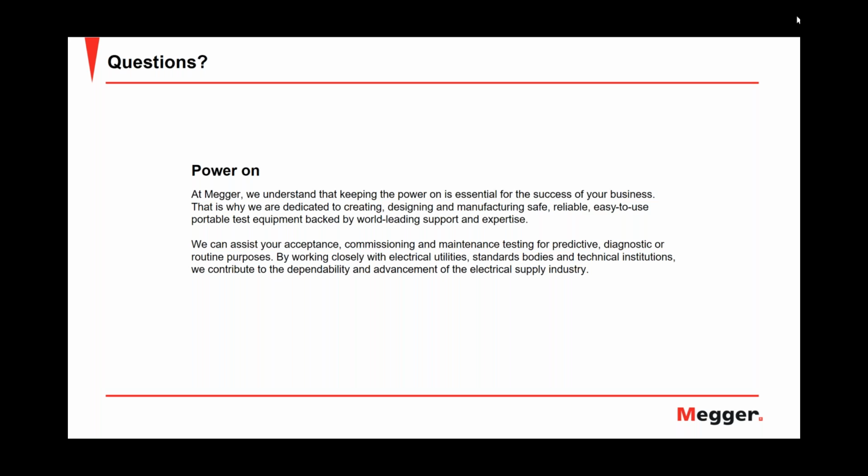Yeah, just to add to this a little bit, because one part of the question also asks about the breakdown. When you do the fault location, going back to the stepped sequence, you use DC, because cable fault location equipment doesn't have an AC source. The basic source to execute all the high voltage functions is your DC source, charging the cap, the burner and everything. So in this case, you only have DC available, and this is why you would do that step with DC.